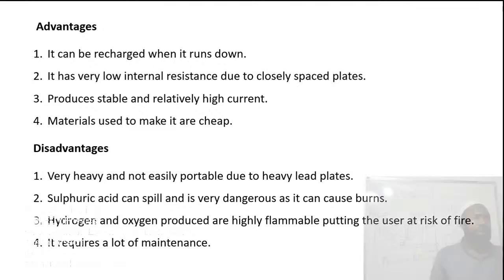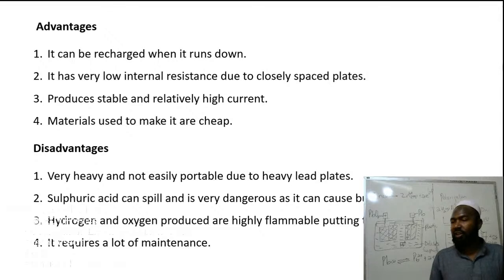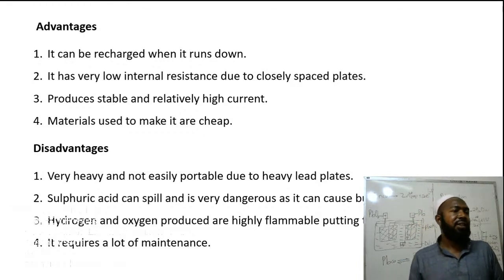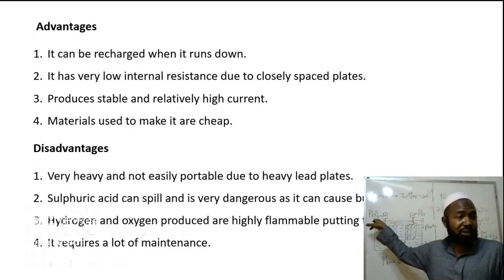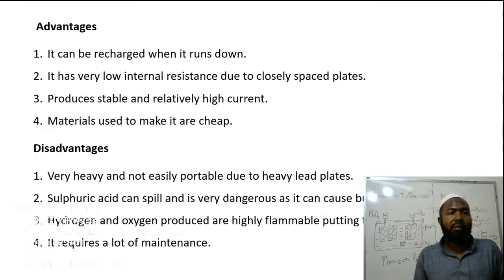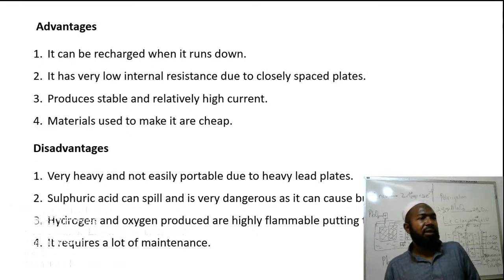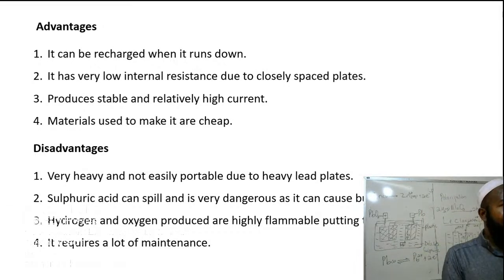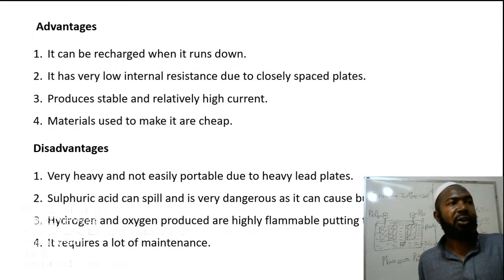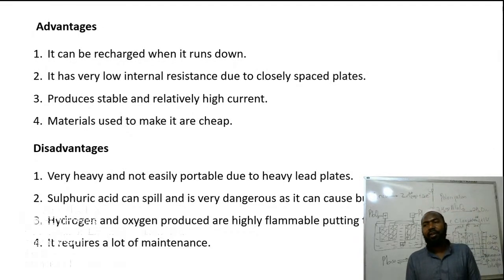Disadvantages: it is very heavy and not easily portable due to heavy lead plates. Even lifting it, you find a hard time. Sulfuric acid can spill and is very dangerous and can cause burns, but usually it is fully covered to ensure that does not happen. Then hydrogen and oxygen produced are highly flammable, putting the user at risk. Then it requires a lot of maintenance, as you are going to see in the care and maintenance of the lead acid accumulator.